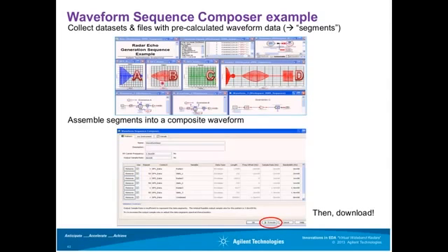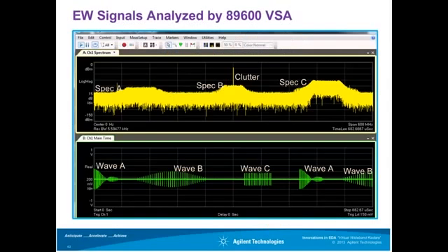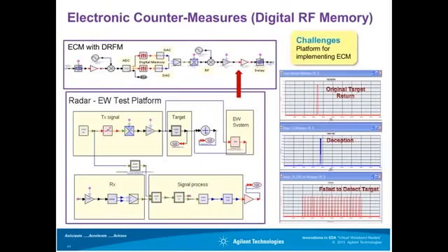At the beginning, you just need to generate simple waveforms 1, 2, 3. Then use the waveform composer to define how long you want to use for A, for B, for C, and insert zeros in between for the transmitter off time. Then use the UI and click execute, and the signal will be generated. Very easy. This is complex waveform generation using the composer.